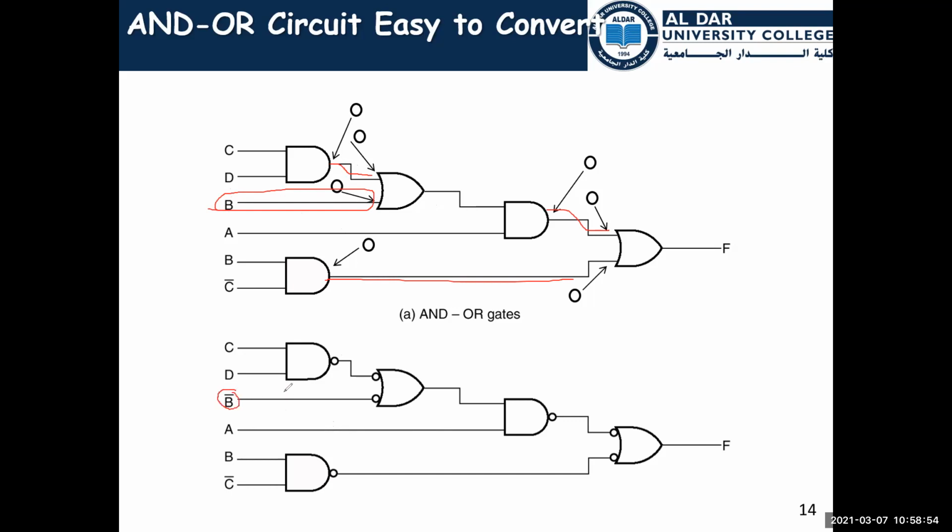It's just to add an inversion, which is the same as adding a NAND gate with the two inputs of it attached to each other. This should be done to avoid having only one bubble.